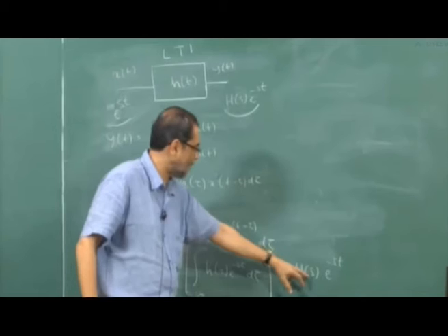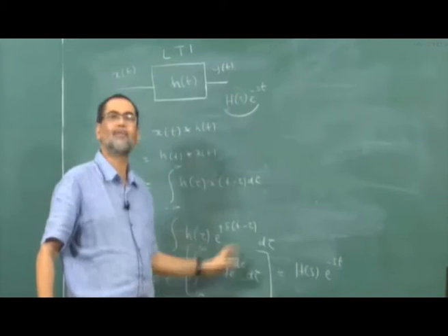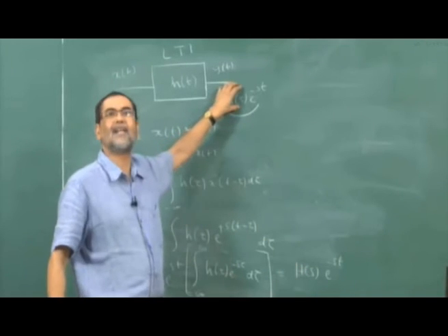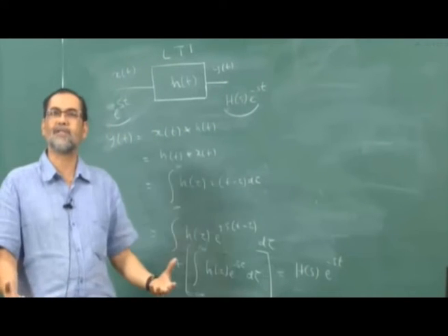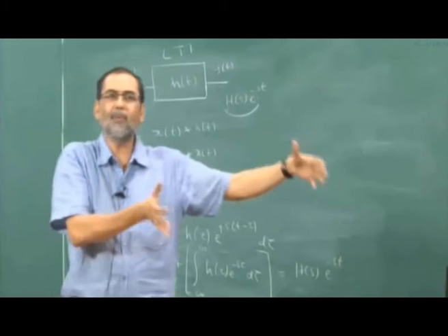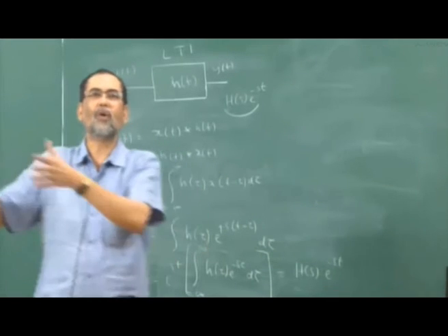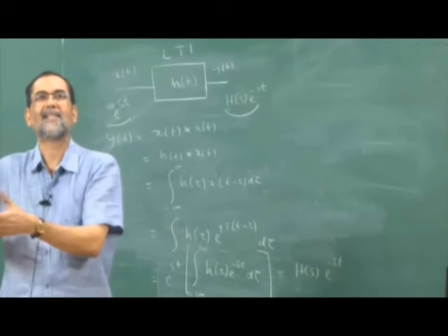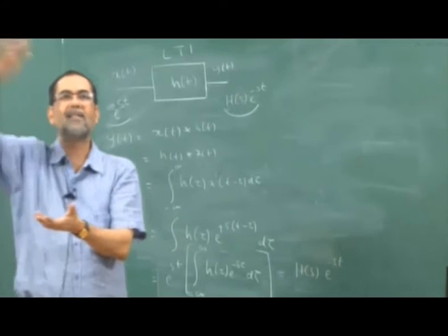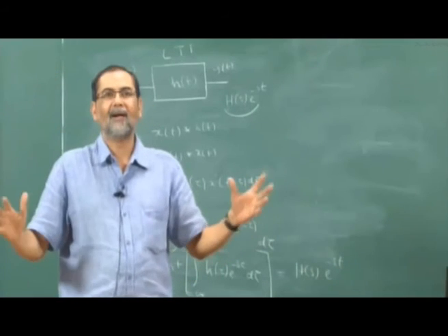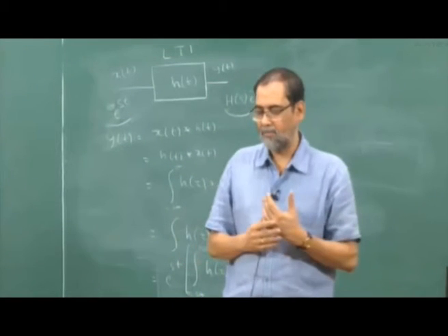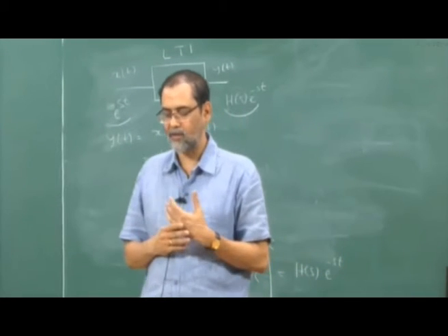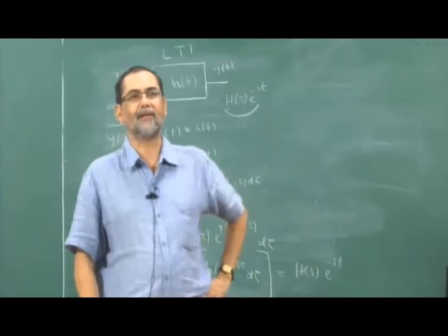Because s is complex, this integral can become complex. So this is a complex scaling factor, which is a function of h, the impulse response. So when the input is e raised to minus st, output also is e raised to minus st, except it is scaled by a scaling factor H of s. This is an idea of immense practical interest.